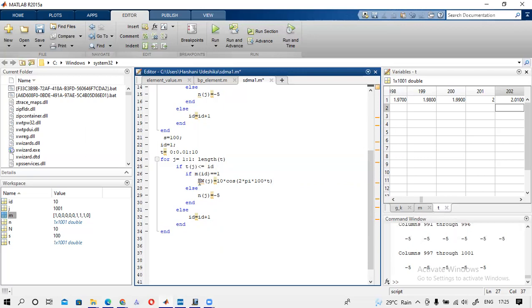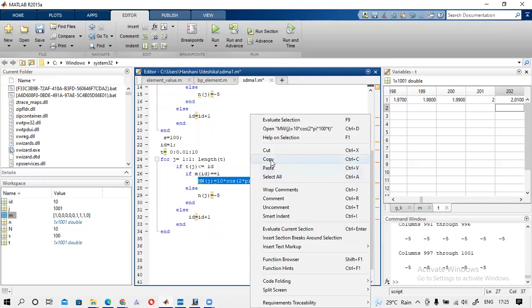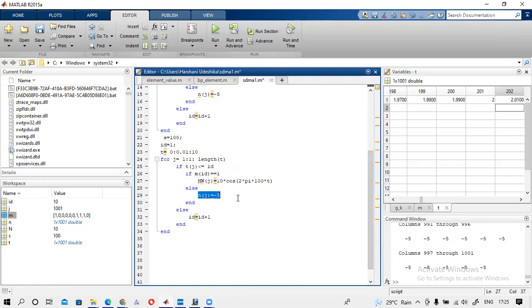And here, if the message bit is not equal to 1, it should be 0. Okay, it should be 0. And if it is 0, we have to put minus A cos 2π fc t signal. Okay, so I think this will work, no issue.